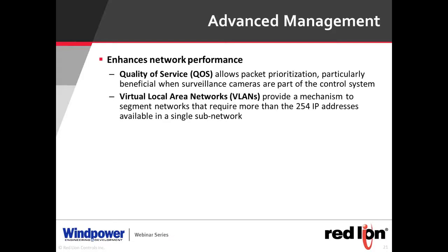Other things to consider, and again, different wind farm networks use different types of products. We have manufacturers using unmanaged switches to monitored switches to managed switches. And while we would advise the use of managed switches because of the capability of rings and diagnostics, certainly there is no one way of doing things.